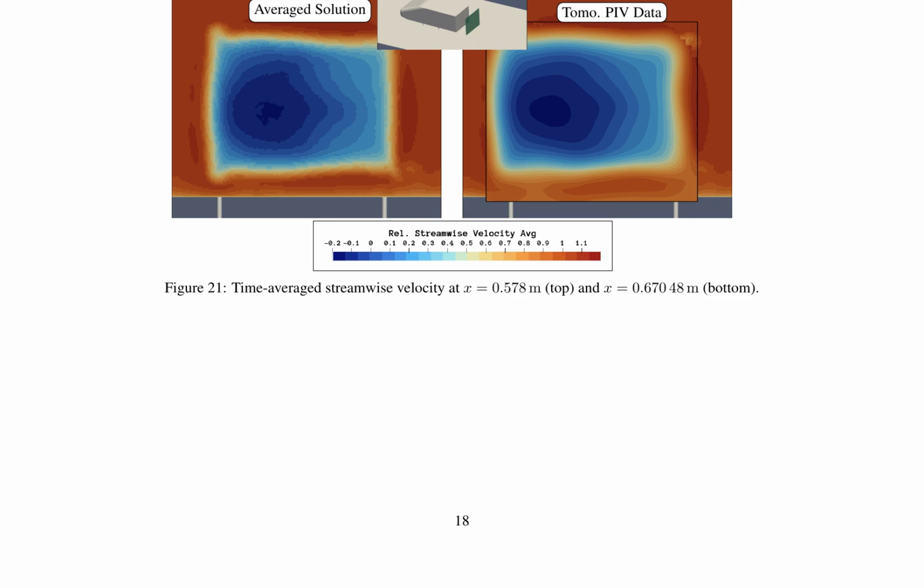The authors utilize the averaged solution tomography approach to reconstruct the three-dimensional velocity field from PIV data, solving the Poisson equation for the velocity potential and employing a Gaussian kernel for regularization. The reconstructed velocity fields are then used to compute the time-averaged streamwise velocity profiles, which are compared to experimental data, showing high accuracy in the near-wall region. This approach provides a detailed, three-dimensional representation of the turbulent flow field, informing turbulence modeling and simulation efforts, and can be extended to other flow configurations and experimental techniques.